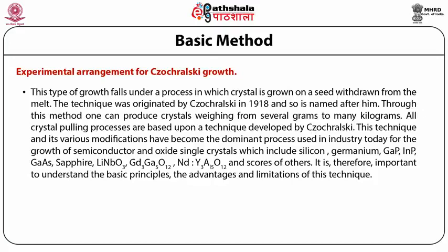This technique and its various modifications have become the dominant process used in industry today for the growth of semiconductor and oxide single crystals, which include silicon, germanium, gallium phosphide, indium phosphide, gallium arsenide, sapphire, lithium niobate LiNbO3, Gd3Ga5O12, Nd:Y3Al5O12, and scores of others.